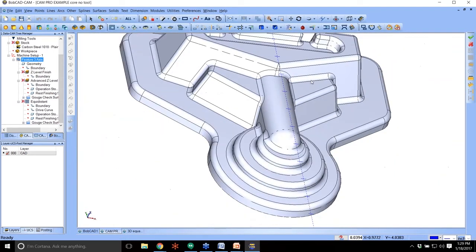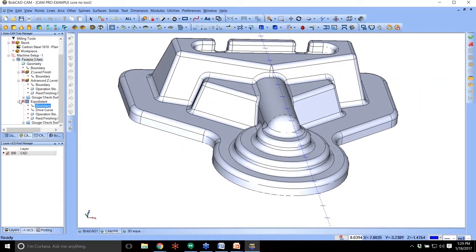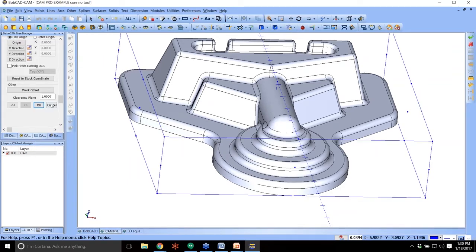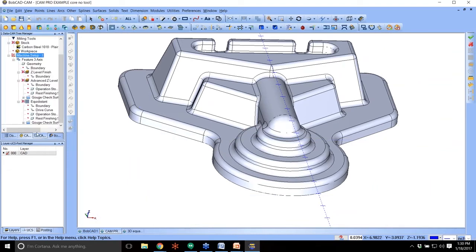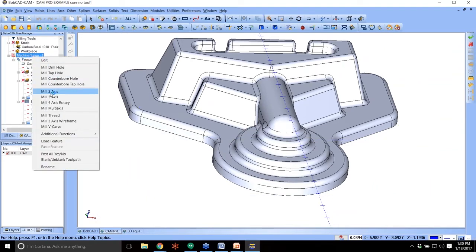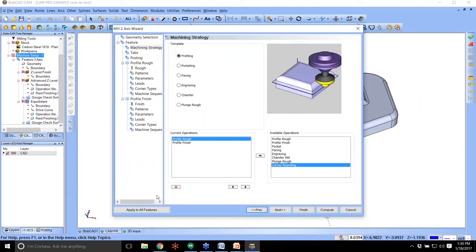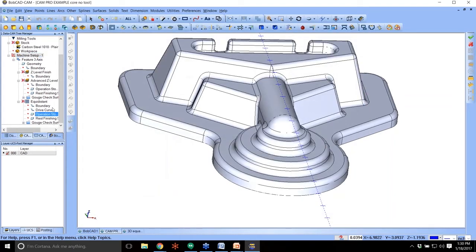Now, another option, too, if you want to, you can go in. So we were talking about angle ranges, okay, and handling fillets. So in filleting, right, if we dive on into the fillet section in here, and we go down to mill 2-axis, we do have the option for you guys to properly output a corner rounding tool with the settings, and it properly offsets and does the calculation properly. But necessarily, we might need to go in and use a ball mill or something like that. So what we're going to do in this case is we're going to go down here,